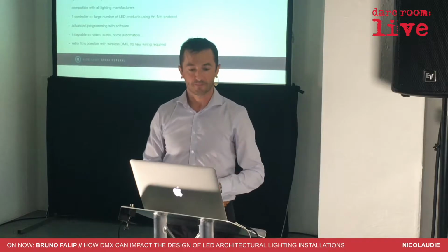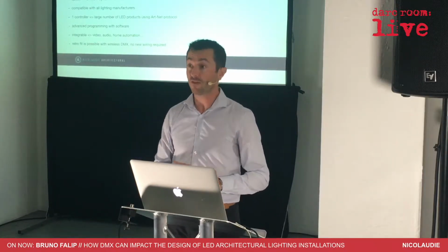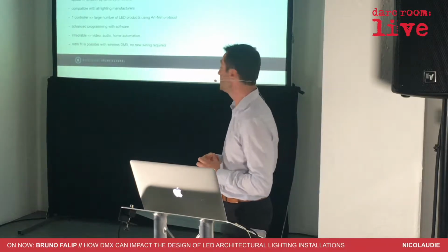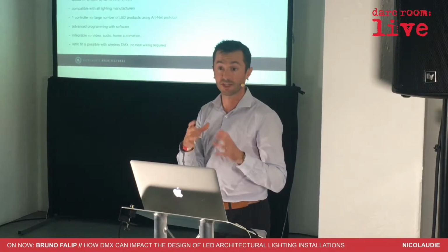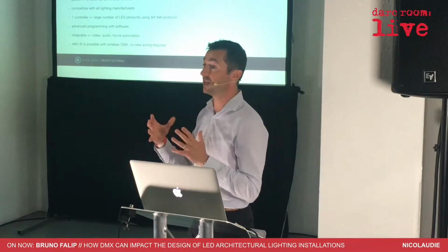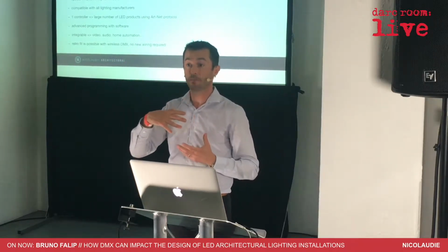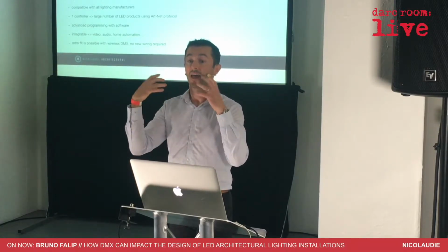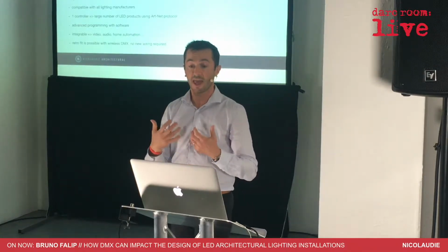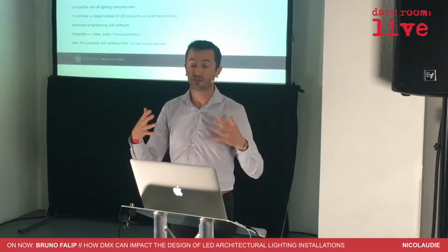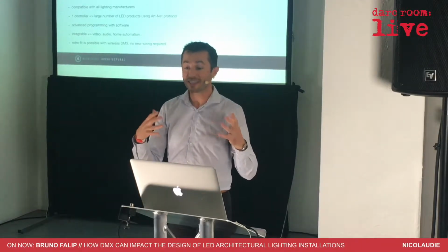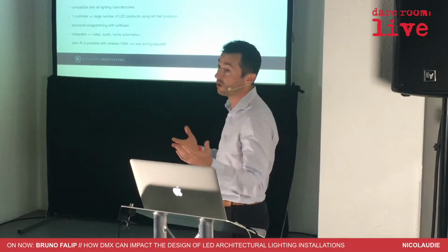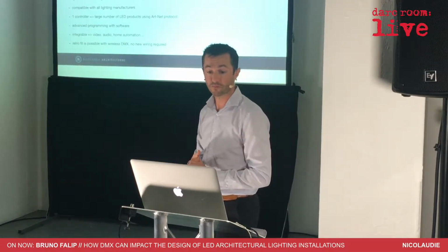So why DMX? First of all, it allows a large number of LED lighting features to be controlled simultaneously. Imagine a big facade for a tower. If you want to play, eventually, a video, you can use DMX to do that, and have all those LEDs synchronized, with fancy, amazing dynamic color sequences for RGB or RGB white, or eventually simple white LED.